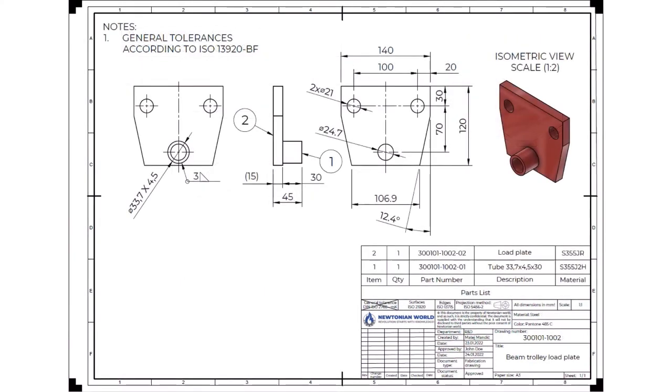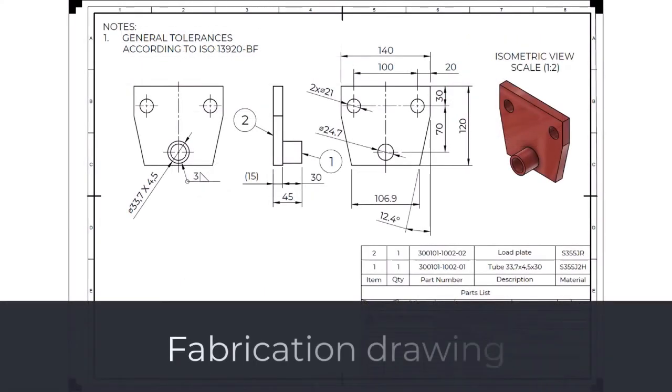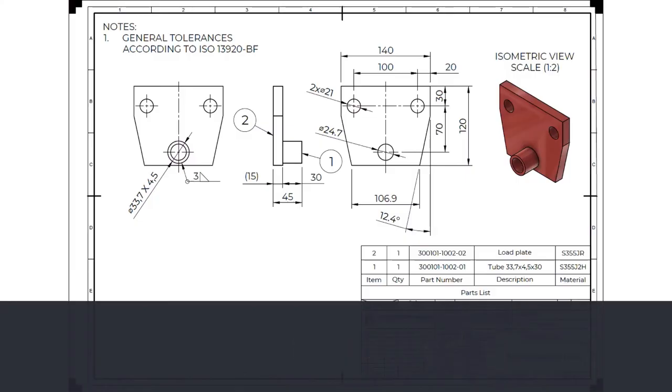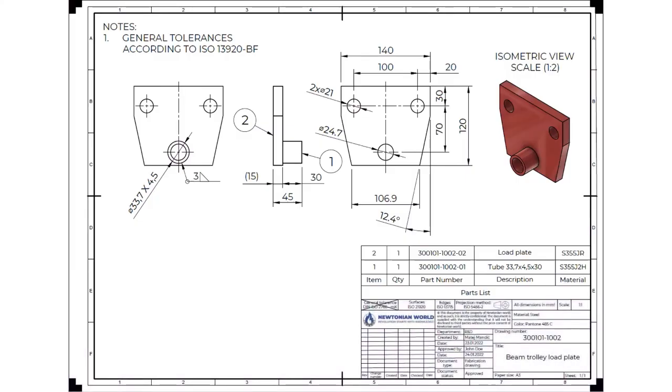The fabrication drawing is defined as the part drawing of an assembly of fully specified items permanently joined together. The components could be joined together by welding, soldering, or adhesive. Every component of the fabrication drawing should be fully specified. Also, the relationship between those components should be defined.